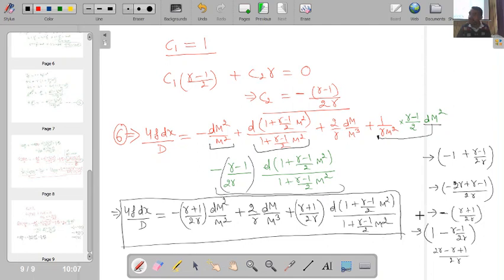So now if you see, if I have presence of friction in small differential element dx, then I have represented that entire equation in terms of nothing but the Mach number. So here you can see that this can give you how much is the change in Mach number. Now if I have to find this equation for the entire pipe, what I will get? What will be the effect on the complete pipe?